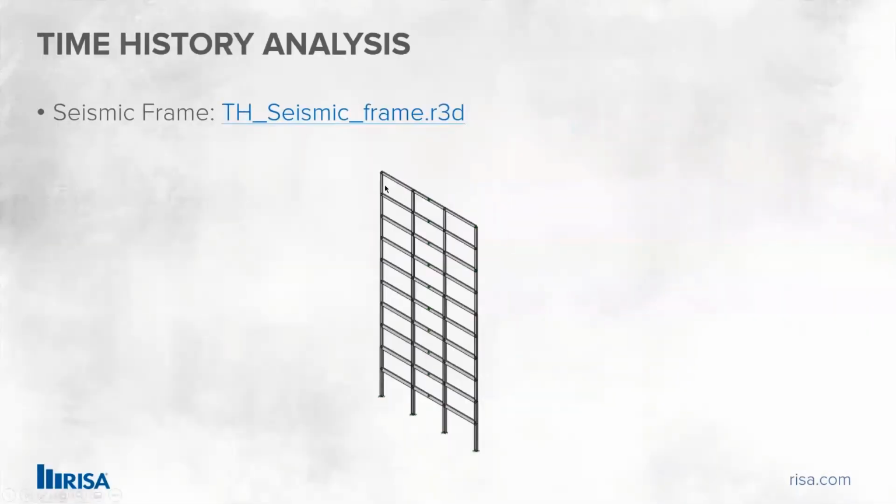The third model is a time history. Since a time history often takes a long time to run, I wanted to showcase a simplified model here. This is just one bay of a moment frame building. So I'm going to apply some seismic load to this building, get a response, and show you how we can view the result.